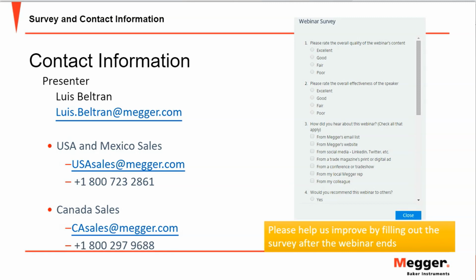Well, when we are using the surge test, there is no standard that talks about the limit, I mean the percentage of the error. So this is something that we can identify in the field. But in our experience, for maintenance practices, we can set the threshold at 5% or 10%.